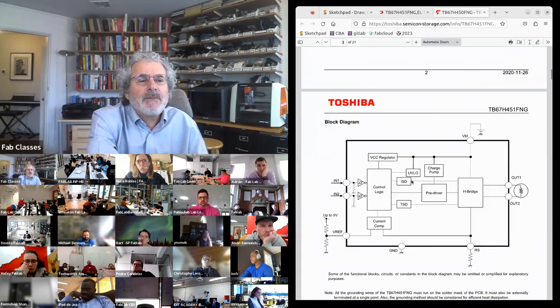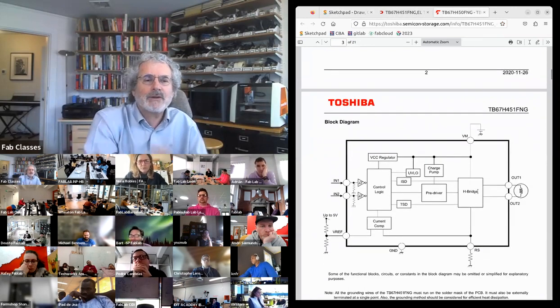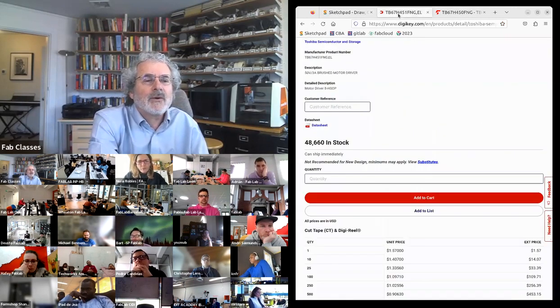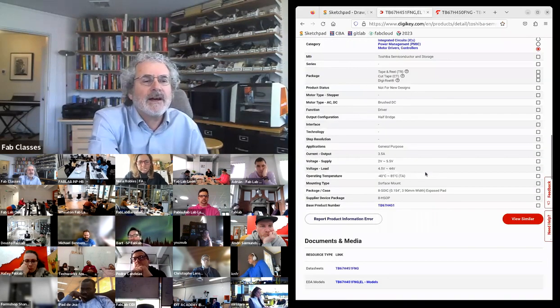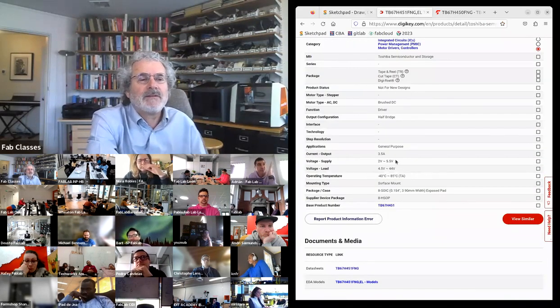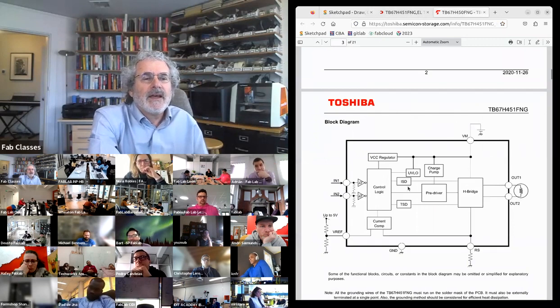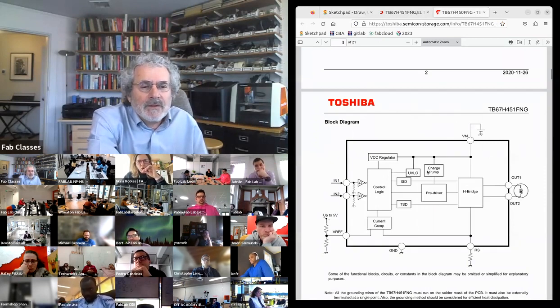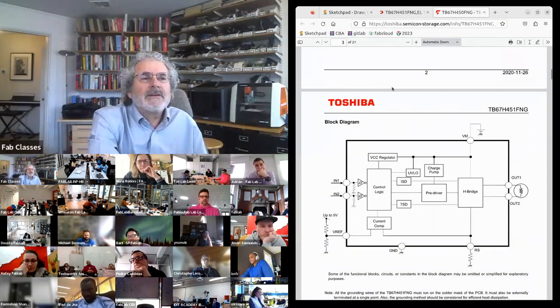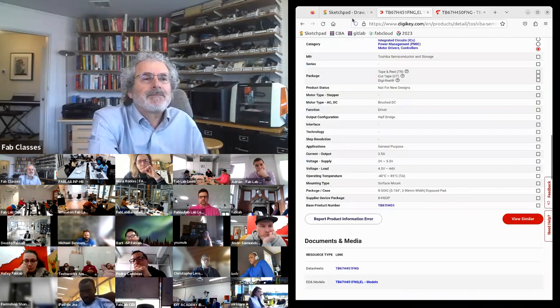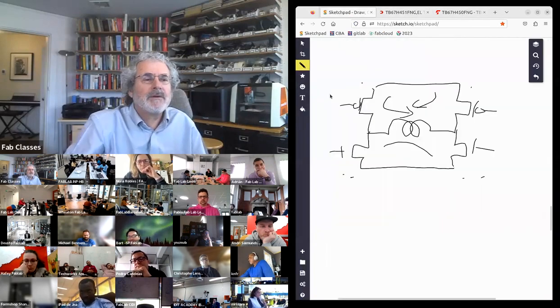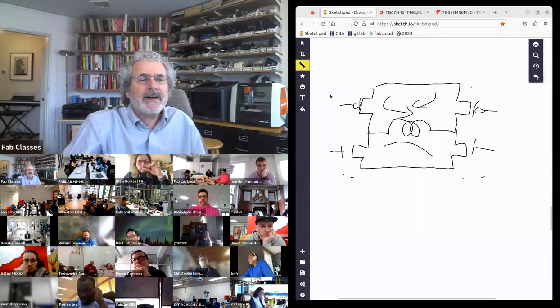Now, what's going on in this package is that's the H bridge. That's the 4 transistors. And they're quite hefty. In this part, it can go up to 3.5 amps and 44 volts. But one thing going on here is the charge pump.